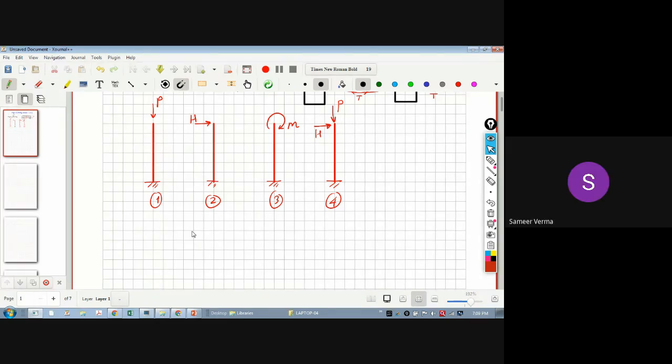So it will buckle. Whenever we say it will buckle, we don't say it is a bending member. We call it an axial force member only, because we don't allow buckling in any columns. That means before buckling, we design in such a way that it will not buckle. That means if it doesn't buckle, then we can say it is an axial force member.